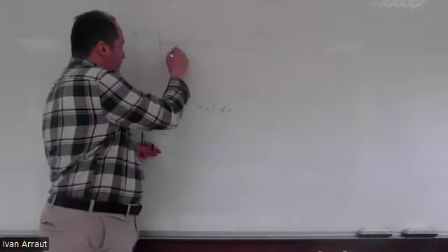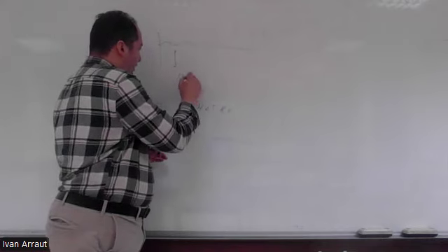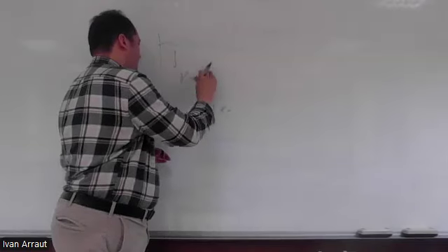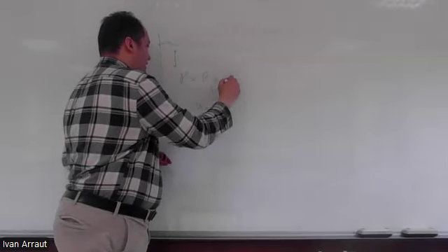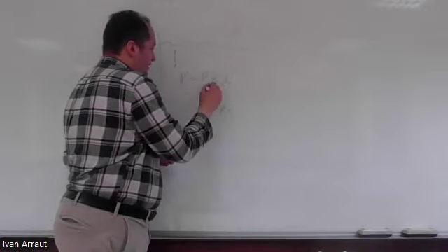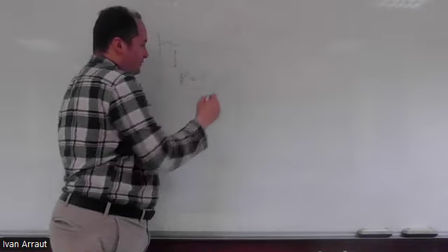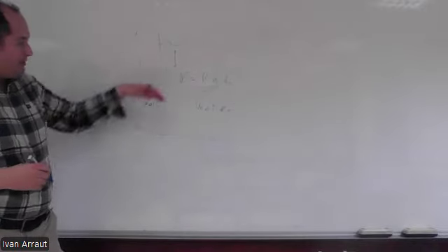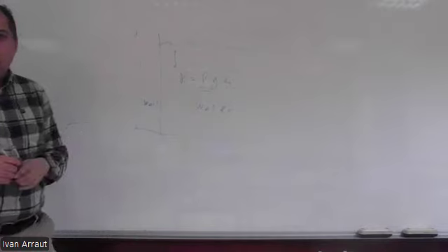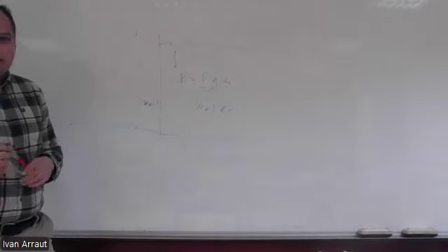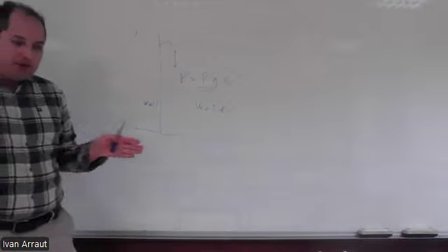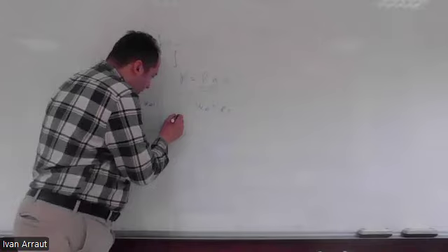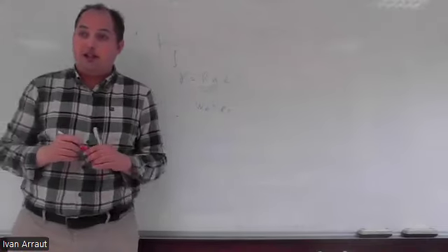Remember the pressure, the deeper you go, the pressure is rho g h. Density, gravity, height. So it means the deeper you go, the higher will be the pressure. We will see that this is the case of hydrostatic. Interestingly, because the fluid is static, it's not moving, each point, if I analyze one point here, is ideally in equilibrium.